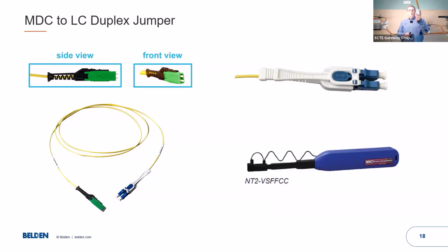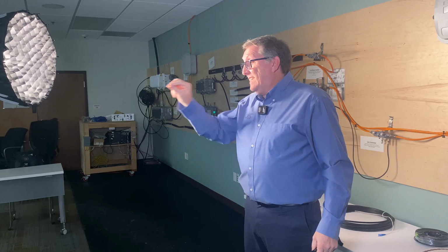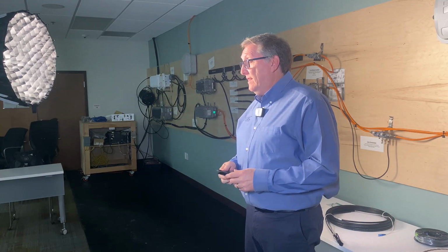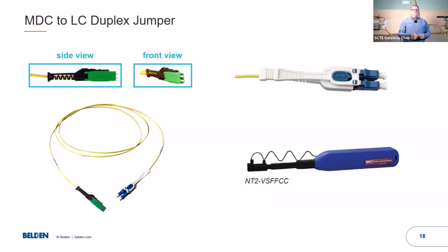The optics are getting newer connectors on the end, where that little white thing you're seeing is actually a handle to help you release the fibers and insert the fibers. If you ever worked in the head end, sometimes switches get really full. And once you put your hand in front of your face to try and pull a fiber, sometimes you can't see where you're going too easy. So these little handles let you see what you're working on. There've been a few mistakes over the years where you put your hand up and everything's really tight. You think you're pulling one, you pull the wrong one. So it's to help eliminate some mistakes.